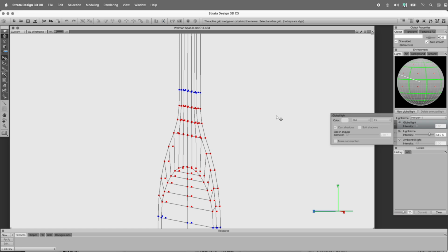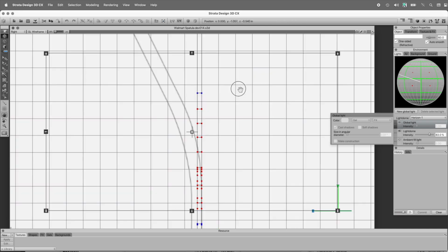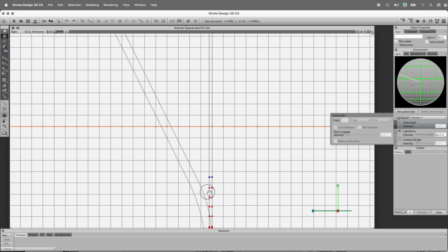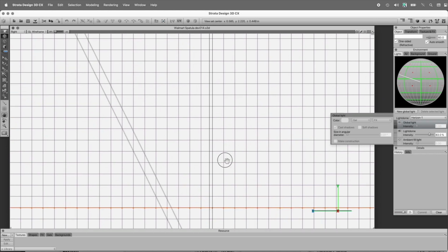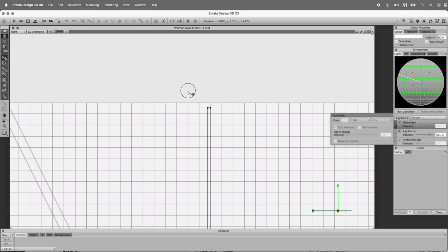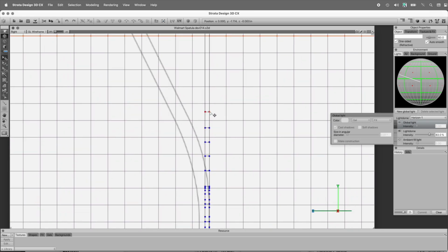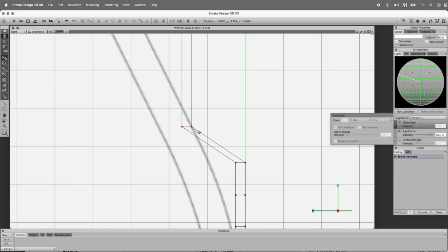So let's look at this from the right, so press the 6 key. So what I'm going to do is the ones that I have selected are going to be bent, but I'm going to take this vertex set here and come all the way to the top of the handle, hold the Shift key, and select these. And then I'm just going to take these and match them up so the right-hand vertex matches basically with the template.